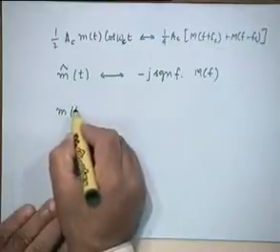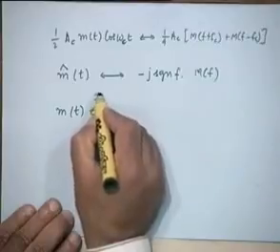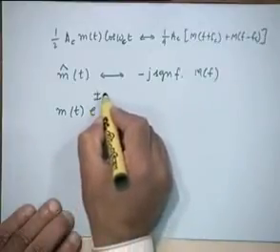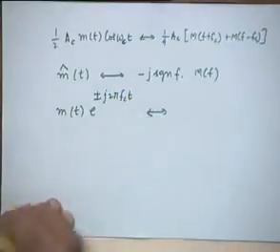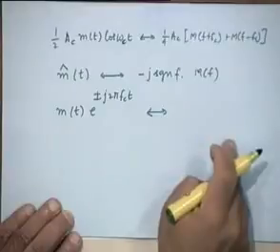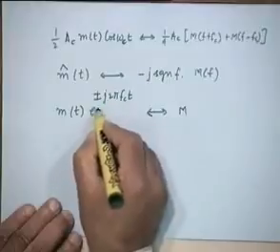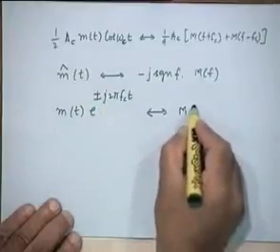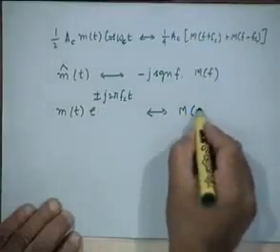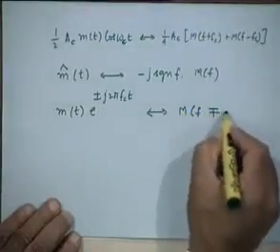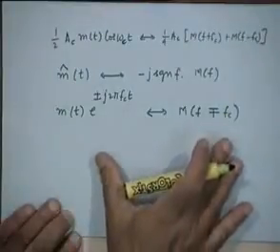Now also recollect the basic frequency translation theorem. Suppose you multiply mt with e to the power plus minus j2 pi fct, what is the corresponding frequency domain relation? When it is plus, e to the power plus j2 pi fct, this will be f minus fc. When it is minus, it will be f plus fc. So this is f plus minus fc. Right? This is your basic frequency translation theorem.